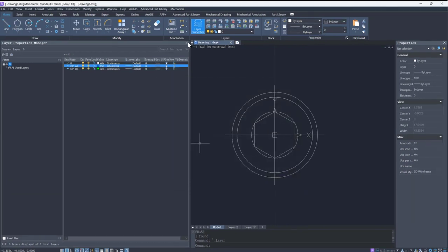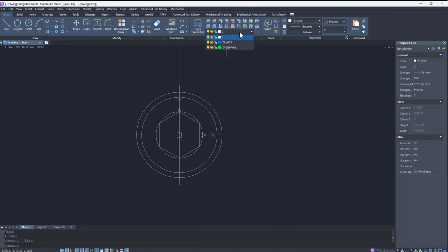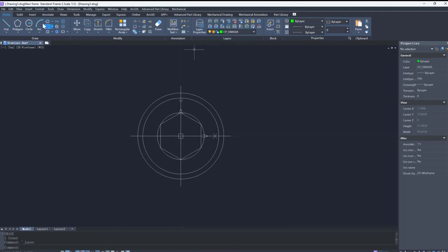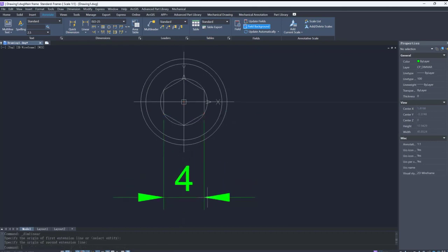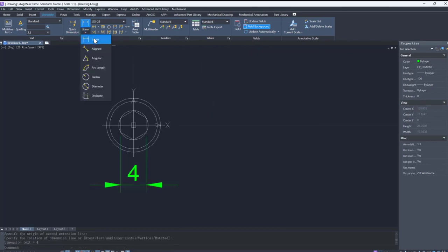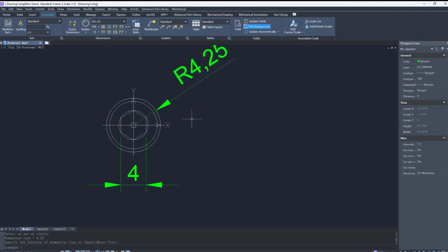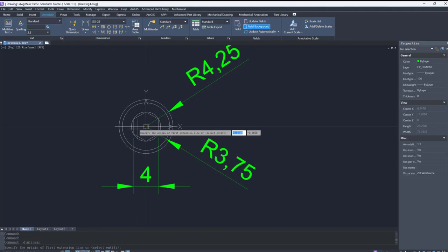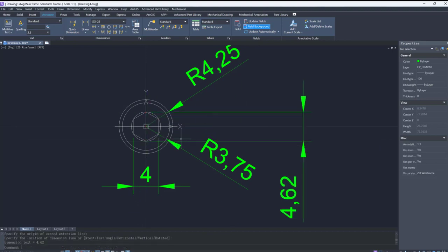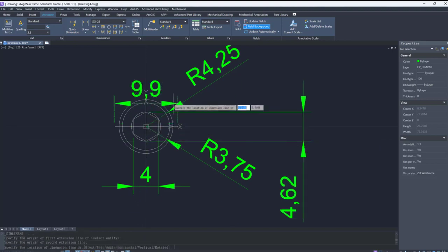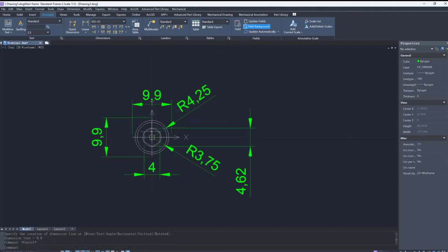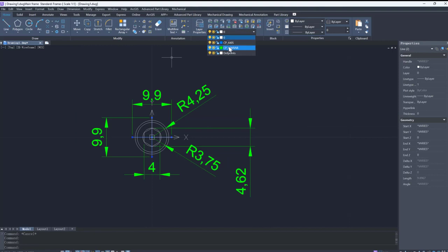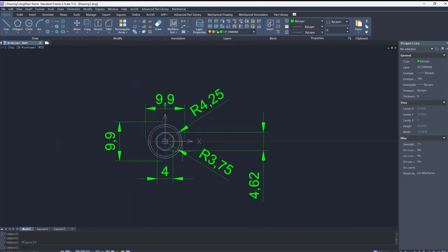The Advanced Part Library uses dimensions as constraints to make all elements parametric. For sizes that will change in the drawing, we need to add dimensions to them. For the head view, we need to add dimensions of 3 circles and a hexagon. As the variables shown in the end are the diameter of the biggest circle dk and the width of the regular hexagon s, we need to connect other dimensions with these two dimensions through geometric relationships. And all the variables must use capital letters.